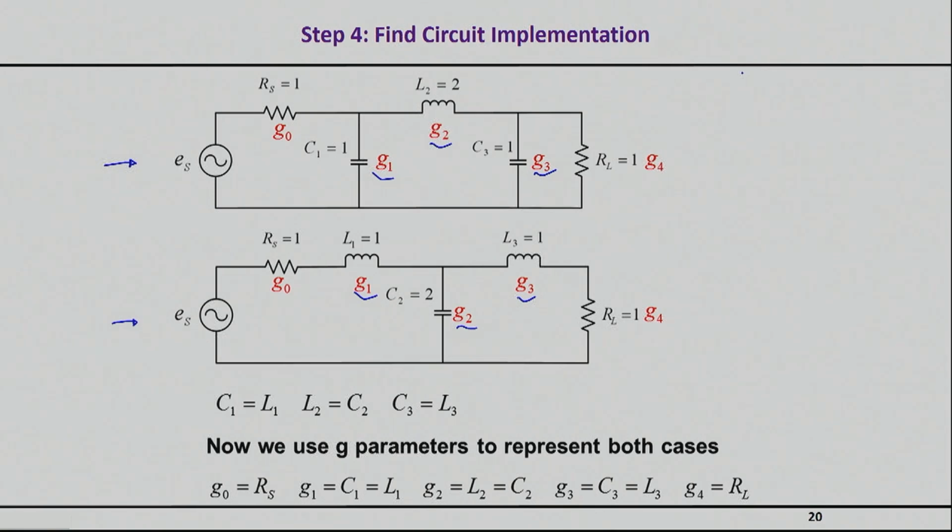Now, why is it important? I mentioned that in many practical cases, one is preferable to the other. The answer is that it really depends on how you want the filter to reject in the stop band. This is obviously a low pass filter. So if I plot the S21 square as a function of frequency, it will yield something like this. This is a Butterworth filter.